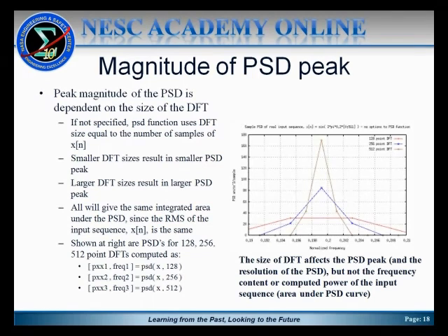under the PSD curve. I didn't show it here, but if you actually took those outputs from those example calls to the PSD function and integrated them as I showed earlier by summing up and dividing by the frequency range of each sample, you get the same PSD of approximately 0.707, which we had showed earlier was the theoretical value that you should get.